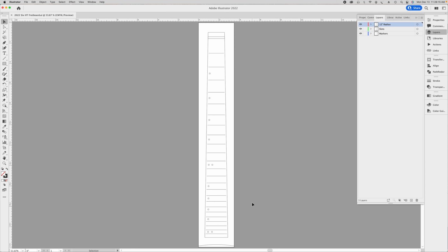And in the case of this fretboard, I'm going to be using 4 different bits, so there'll be 4 different carving operations. Now, to make sure that each operation is positioned properly with respect to the previous carving operations, I want to make sure that all of the carving operations are centered within the blank.